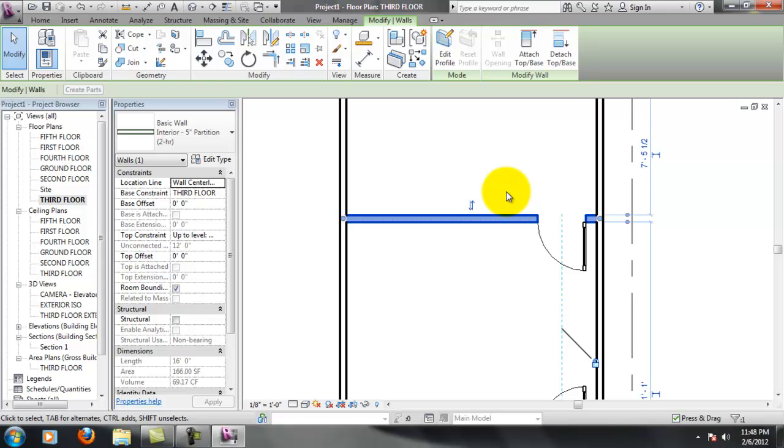And obviously Revit isn't going to have that detail, so it's important that you learn how to create your own wall types when the situation arises. Now, it's not going to work so well in your favor for details necessarily, but for elevations it'll definitely save a lot of time and make things look how they're supposed to look.